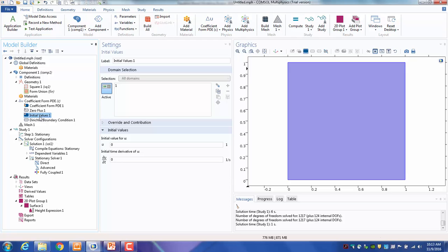So these equations are potentially nonlinear, right? In this case, we are solving a linear problem. But think of solving a nonlinear problem. What happens? The weak form will convert this, and then when you add the finite element discretization, at the end what you will have is a system of nonlinear algebraic equations for the nodal values. So when you have nonlinear algebraic equations, you're going to solve them using a Newton-Raphson or other method like that. And there, you're going to start with an initial value and iteratively try to get to your solution.